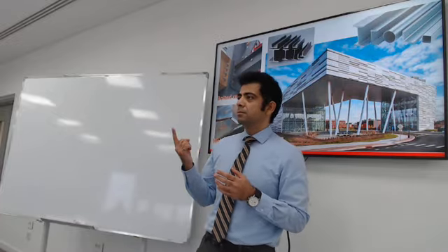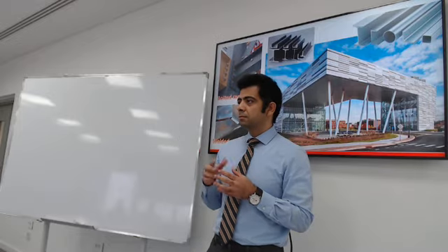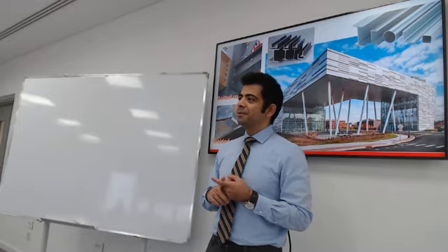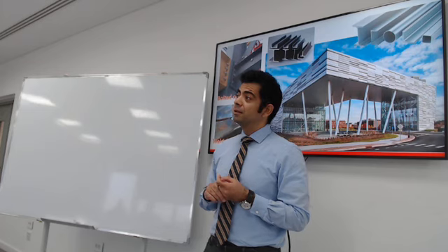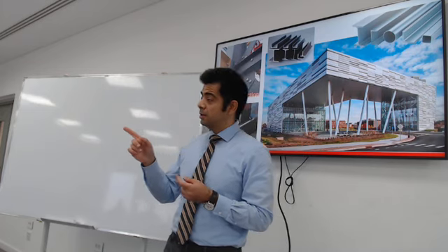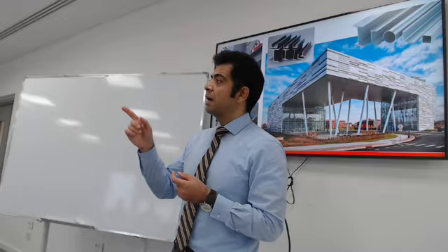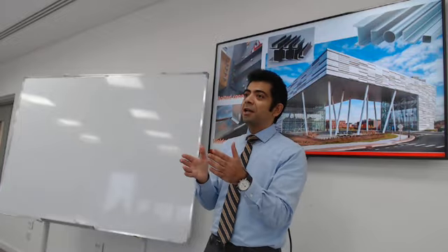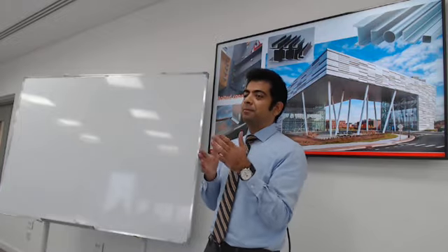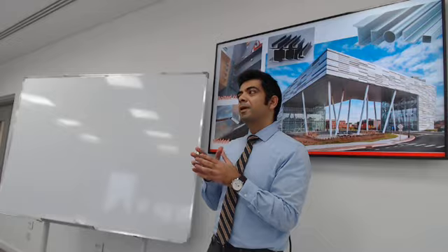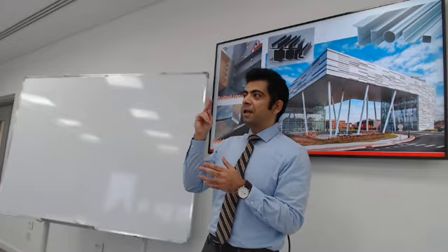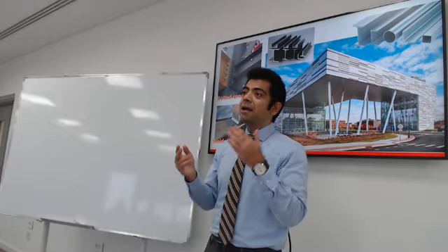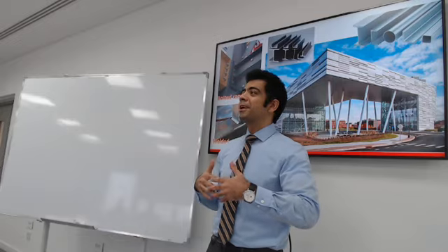Find the load. Yeah, you definitely need to find the load. Then what? Then choose the section. Then validate if it will carry the load and hold the moment. Yes, then make sure that the section is valid and is strong enough. What are the 2 limit states that you designed the section for? Ultimate limit state, make sure that it's not going to fail in bending or shear, and service limit state, make sure it's not going to deflect too much.